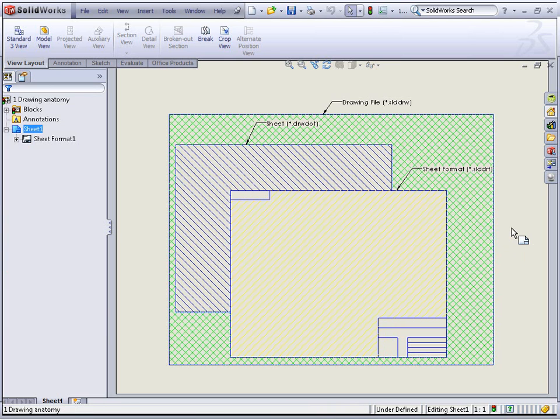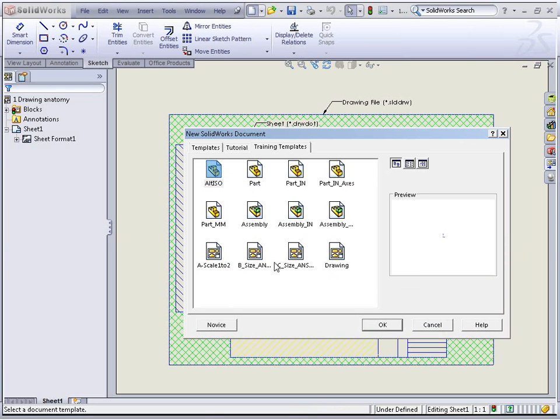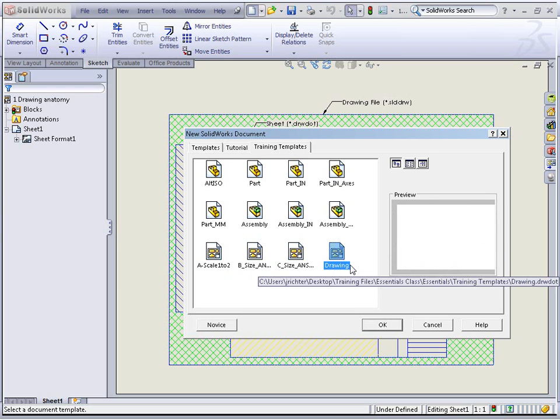When you start a new drawing in SOLIDWORKS, when you open a new drawing, the first question it asks is which template would you like to use. I've got 4 templates here. 3 of these are merged templates. That is, they have the title blocks pasted right on top of the blank page. This is inappropriate for most cases. Your drawing should behave like this one, the blank page.